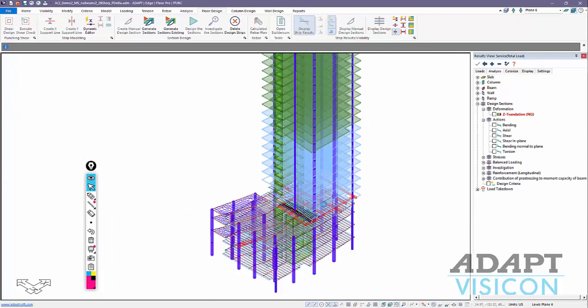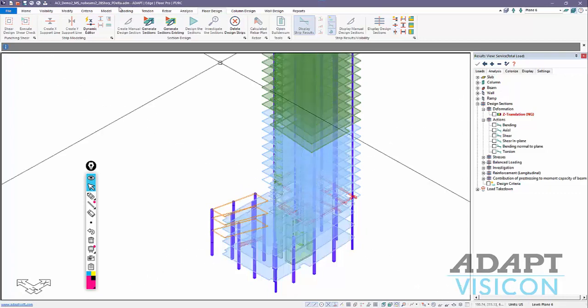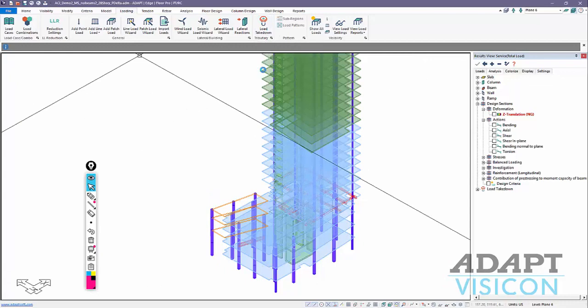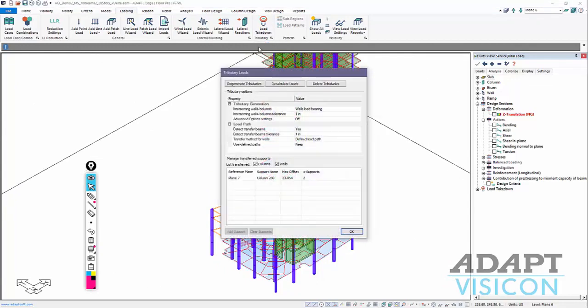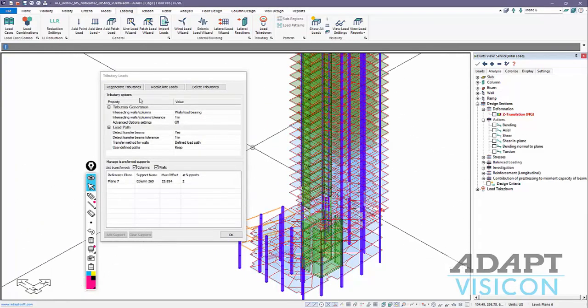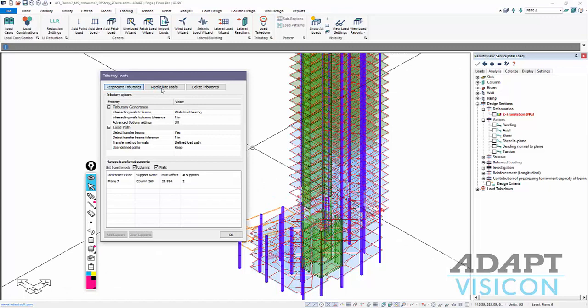So if I take this model now, which includes loads on all levels, and I use load takedown, I'm going to generate Voronoi-based tributaries for the structure. And so we'll regenerate and recalculate the tributary load takedown based on these tributary regions that the program has produced. And the user could go level by level and dig into some of the results using these load takedown tools in the result browser here. I'll recalculate the loads.